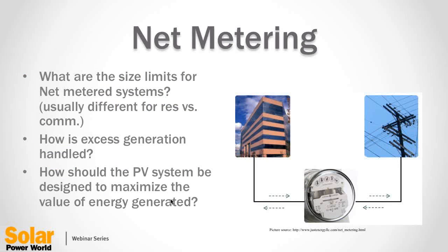The way that it's metered, the value you get for the electricity exported, or your net excess generation, varies based on whether it's residential, commercial, or even just based on size. So it's really important to understand that. Hand in hand with net metering goes what the customer's tariff is. I've seen time and again where you may know your solar, you may know net metering, you may have put in a lot of systems, but every customer is a little bit different, and depending on what utility they're on and what their rate tariff is, that has a big impact on the technical viability and financial viability of a project, to understand what they're being charged for or not being charged for.